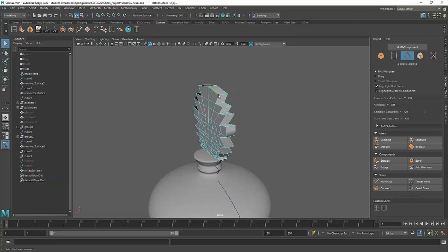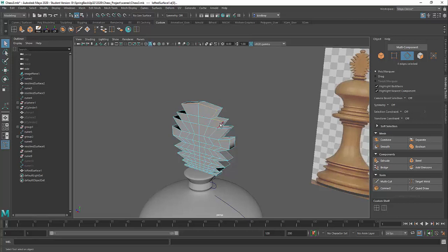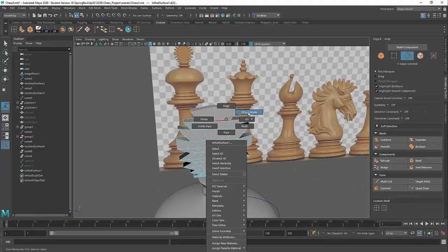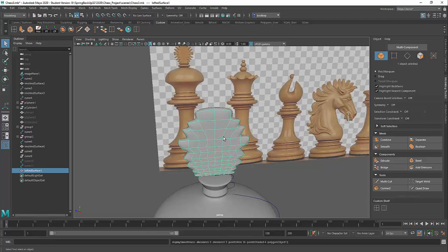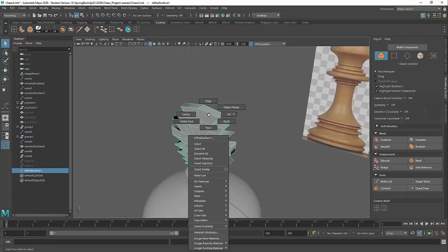So I could do that just by going around and holding the shift key and selecting each one of these. And I'm not going to do that here, but I would bevel that again just by clicking on the bevel tool. I'll do one just to show you, and then I'll undo it, but like add a little bit of fraction there. But again, I would do that to the whole thing, and then perhaps add smoothing, with number 3 to smooth it out. Maybe add a few more edge loops to firm up the areas, but I think doing the bevel should do that actually.